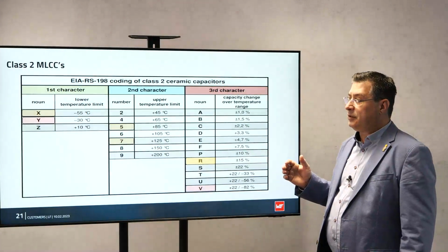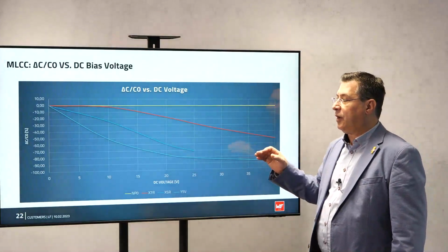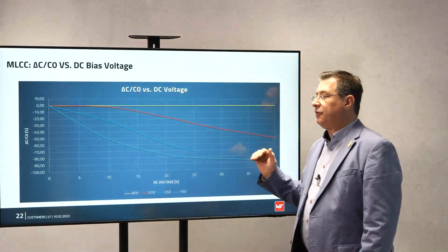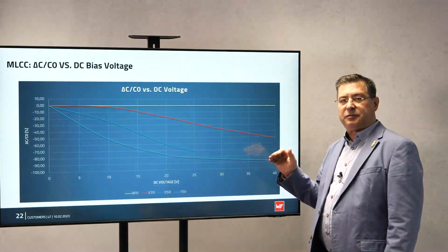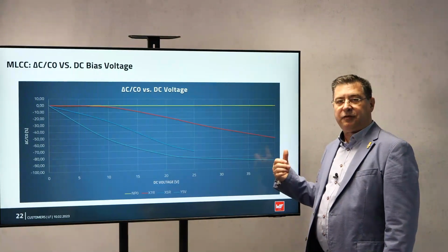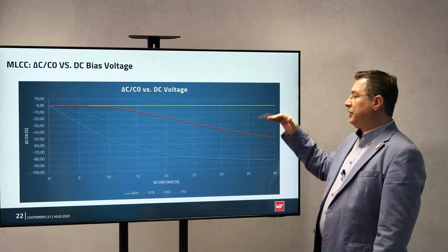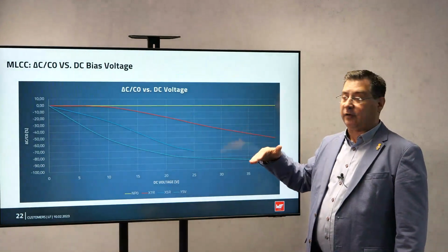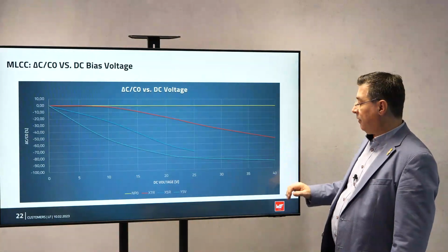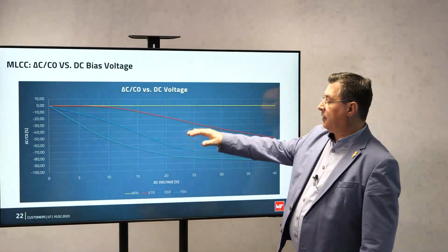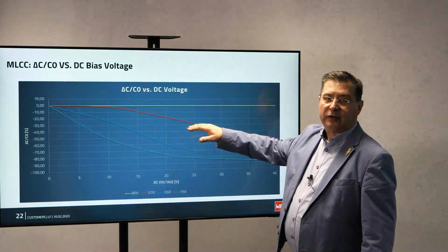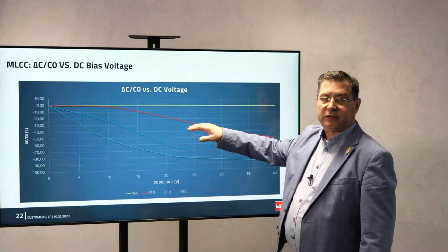But if you consider these different capacitors together and you look at the same value, you see that X7R to X5R have a big difference by the DC bias voltage. Like a 50 volt NP0 capacitor, you pay a lot, but you have no drop of the capacity. If you use an X7R 50 volt and you are using it at 25 volt, you have almost already more like 20%, almost 30% drop of its capacity value.